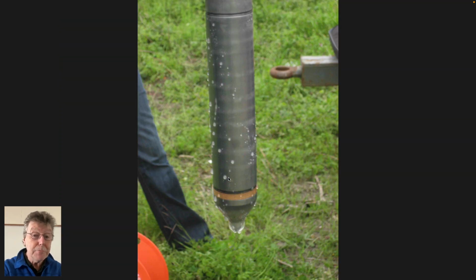This is the cone at the tip. This is the end bearing. There's a load cell behind this that measures sleeve friction. There's a porous frit here that allows you to measure pore pressures outside here. You need to keep it saturated before it goes in the ground, so you saturate this porous frit with some silica gel. Do you know what the sheath is that's on this?